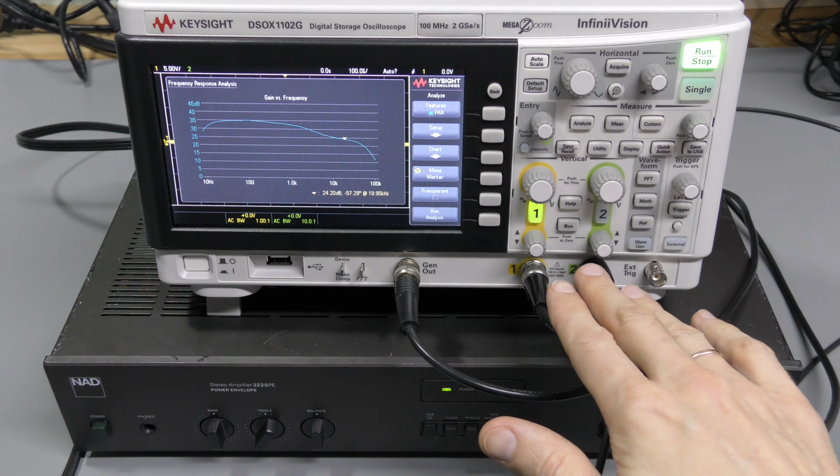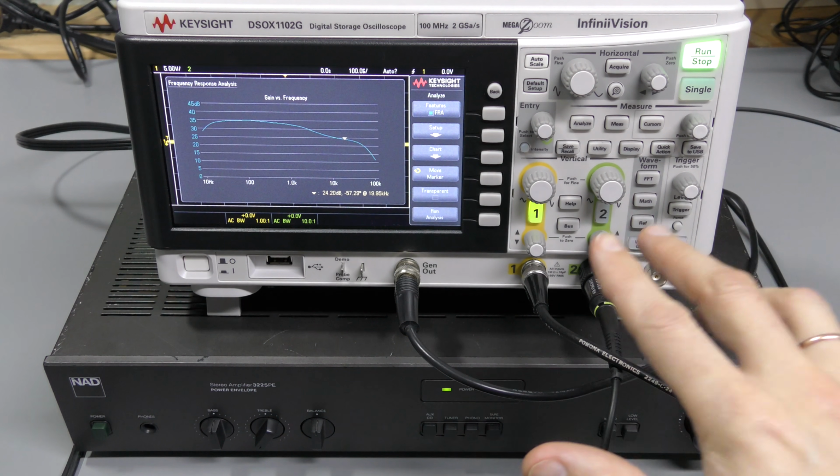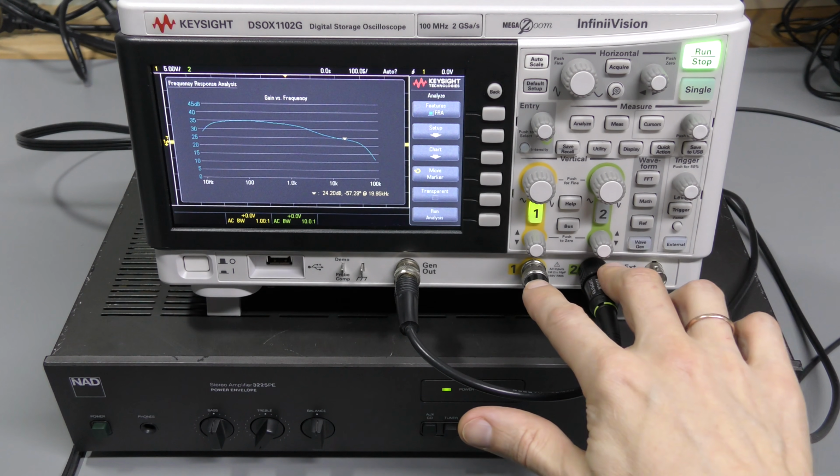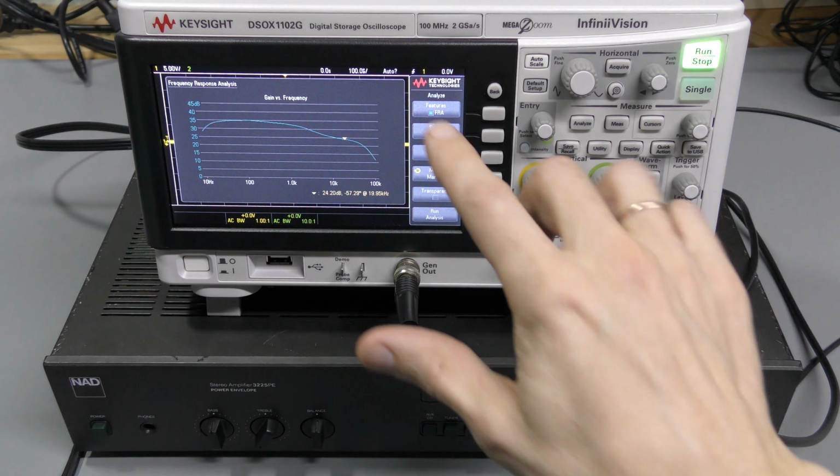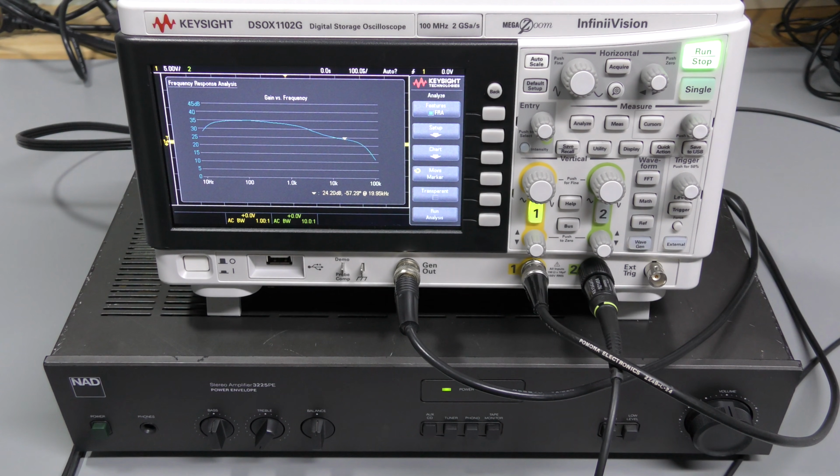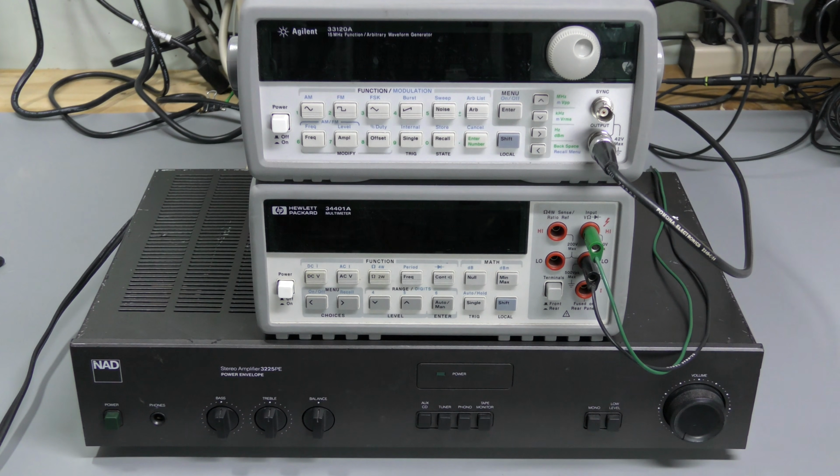So this is a much better way, and we still have that 8-bit front-end limitation, so this is not super precise, but for this purpose it is just fine. Now let's talk about some other ways. One more way would be to use a computer sound card. Plenty of resolution, at least 16 bits and maybe 24 bits, and a wide variety to choose from, starting from built-in and cheap to external USB professional recording interfaces.